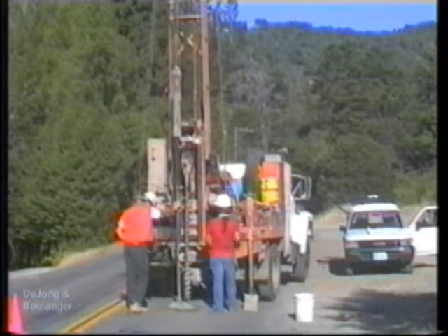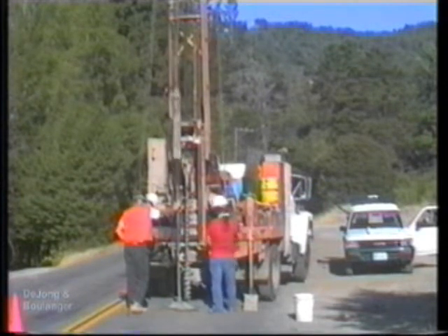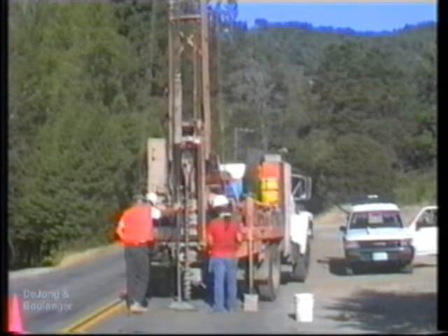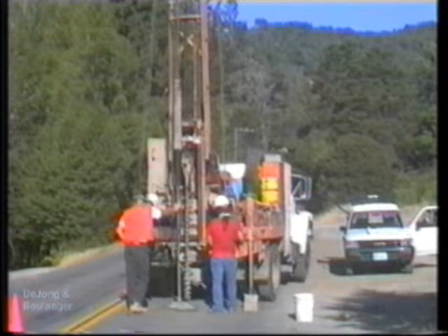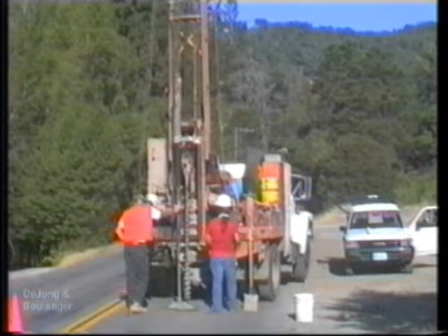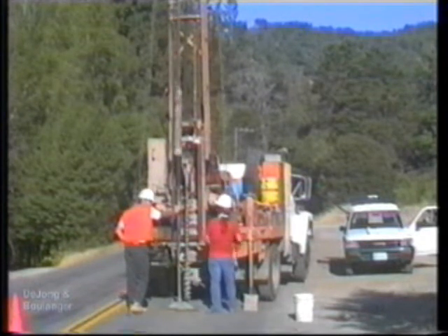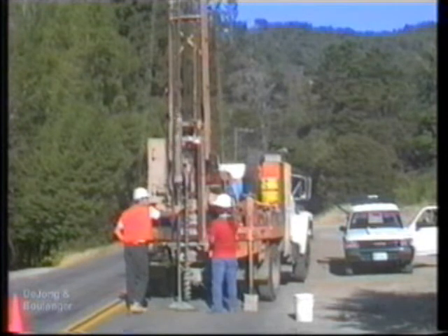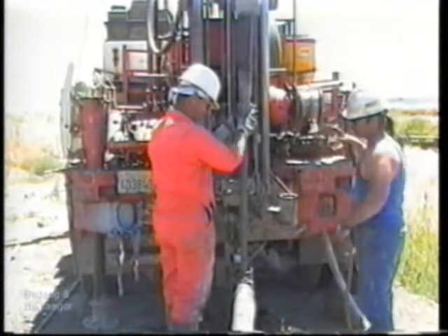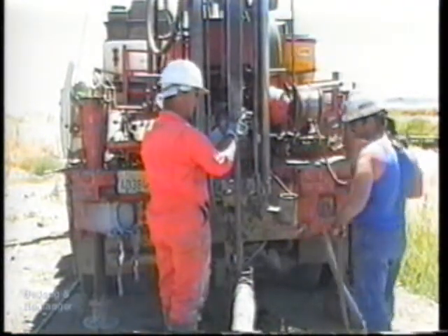The amount of energy delivered is dependent on many variables, including the type and weight of hammer, distance of free fall of the hammer, size and length of drill rods, tightness of connections, weather, and operator. If using a cat head and rope, the energy also depends on the condition and type of rope and the number of wraps around the cat head. If using a trip hammer, the energy also depends on its condition and type. The amount of energy delivered can range from 30% to 95% of the theoretical maximum.